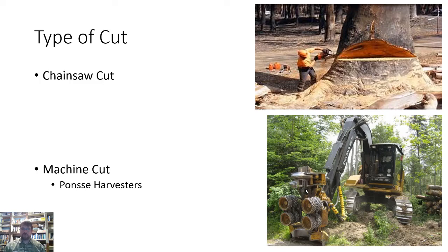There's also a guide in there. Often it's a laser guide or a wheel guide that tells you the distance. So you can start, you cut it, okay, lean it down, run these wheels down it, delimb for a certain distance, cut it there.